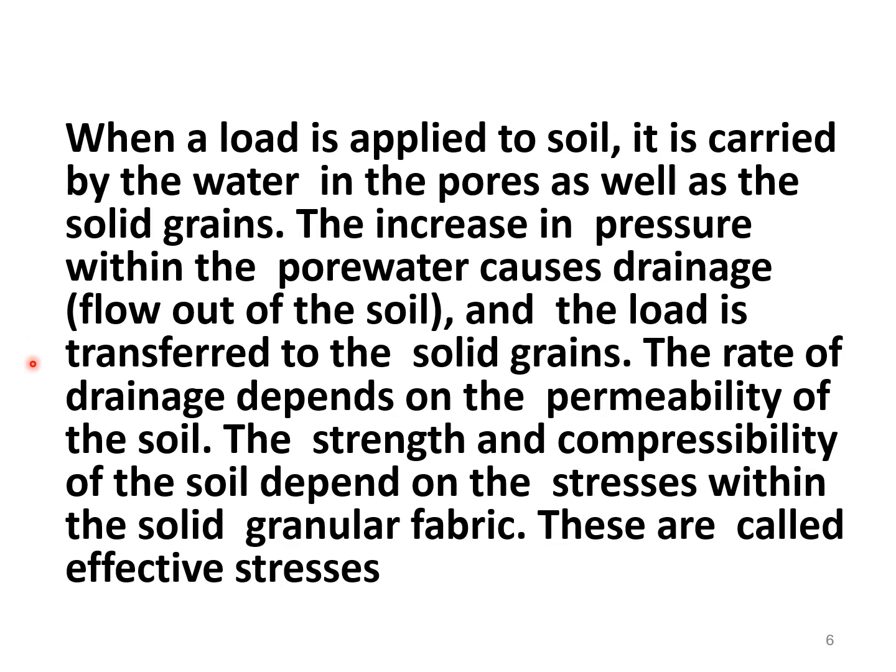The rate of drainage depends on the permeability of the soil. The strength and compressibility of the soil depend on the stresses within the solid granular fabric. These are called effective stresses.